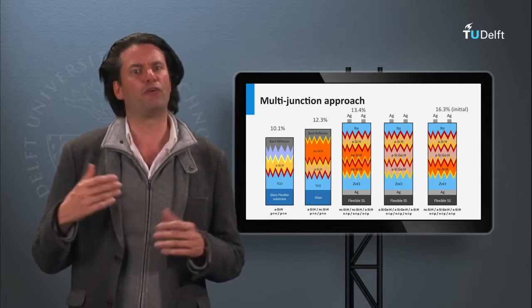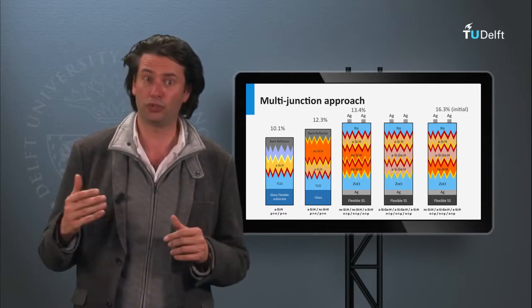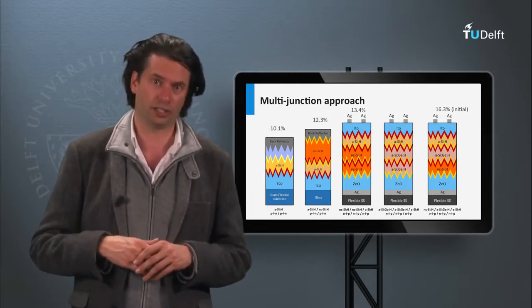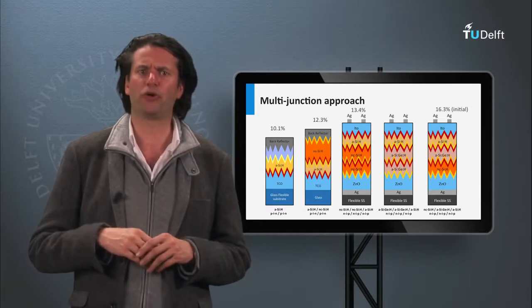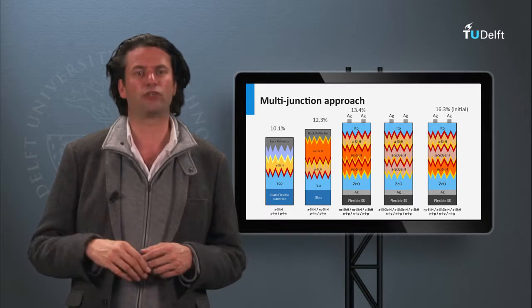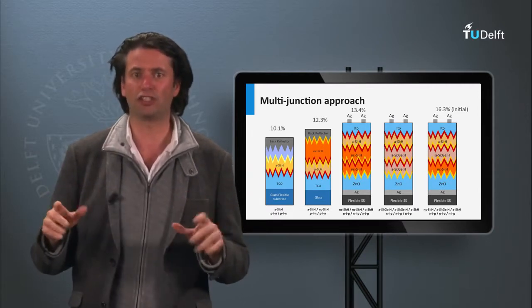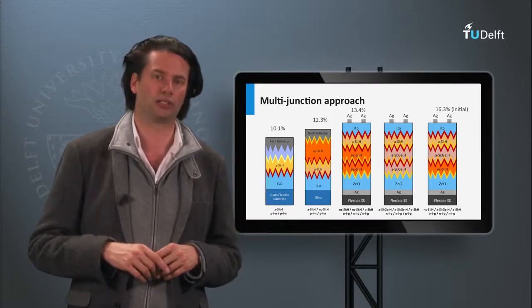The performance of amorphous solar cells relatively decreases by 10 to 15% due to light-induced degradation, and therefore people talk about stabilized efficiency. If the Staebler-Wronski effect could be tackled, thin film silicon devices could achieve efficiencies well above 16%.